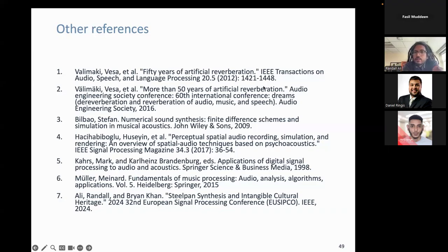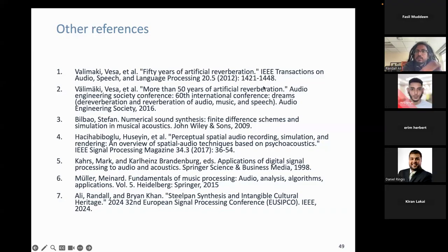There are particular methods and standards for doing this. Of course, you need really quiet spaces. Sometimes when we've done these measurements, we've had to do it at night when there was not a lot of noise in particular spaces. But then we ran into the problem that there are a lot of crickets and frogs making noise outside, and that also affected measurements. So ideally, a quiet room and good quality microphones and loudspeakers.